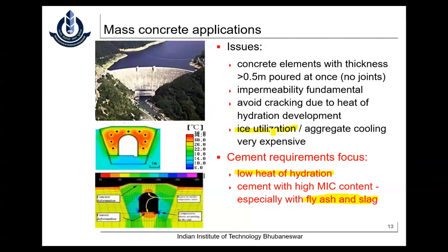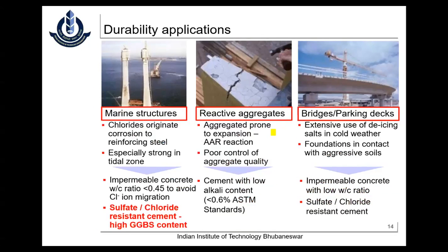And also, definitely nowadays we talk about the durability that you mentioned initially. Now things have gone beyond our control. Strength-based design has gone completely, and people are talking about durability-based design. Let's say you have marine structures, or a structure near the coast. Definitely there are a lot of chlorides and all this, and without any hesitation I can say, I'm not saying a brand, you can use a Portland slag cement. I'll show you some slides of how much resistance the slag cement gives when used for marine applications.